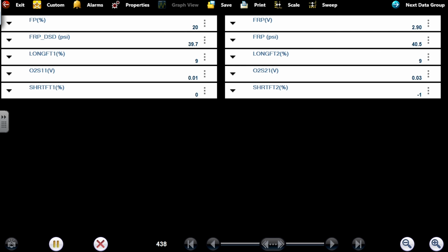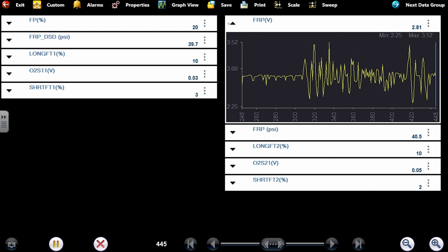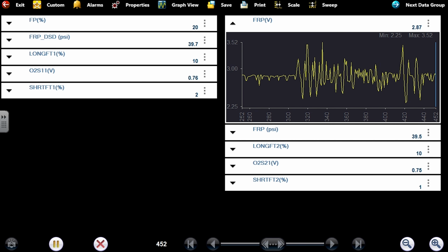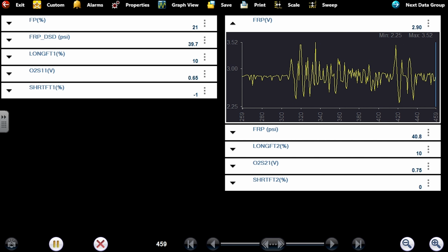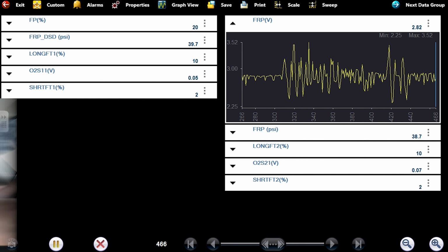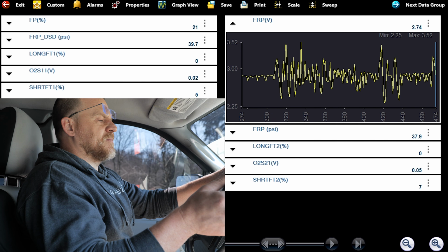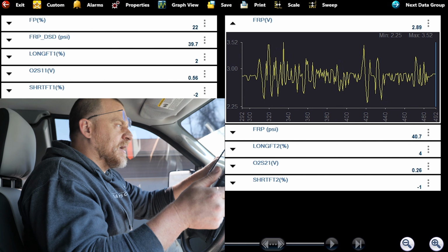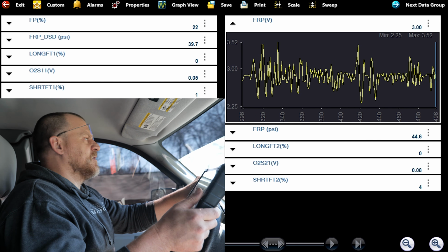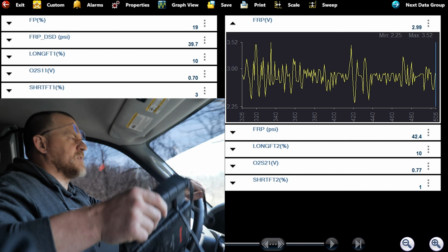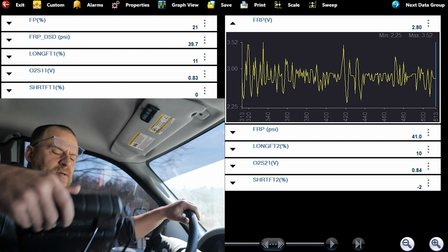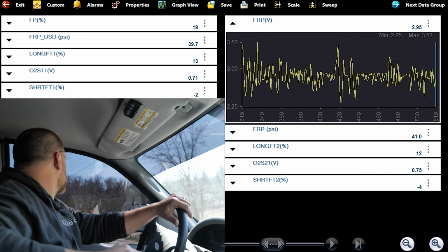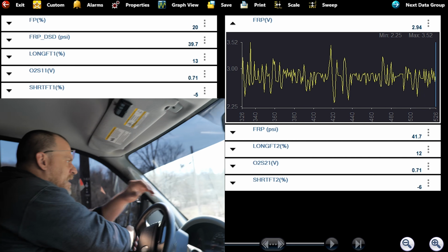All right, so you guys know what we're looking for here. Again, fuel rail pressure. And then you're going to see it right away. I'll just leave everything else alone. You'll start seeing the short-term fuel trim go positive when we start losing fuel pressure. I'm anticipating us losing fuel pressure. What we don't know is the cause yet. We don't know the cause. We are prepared as much as we can be.